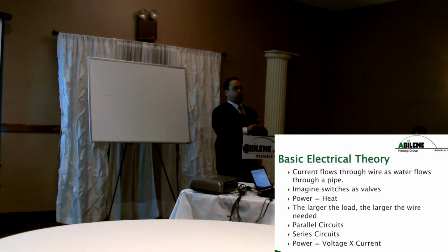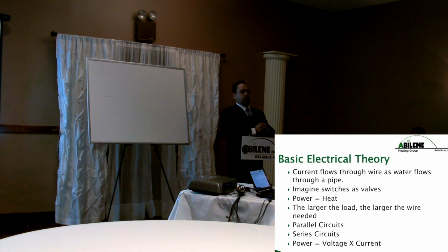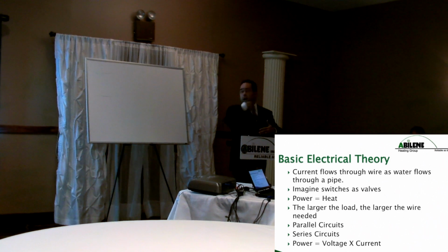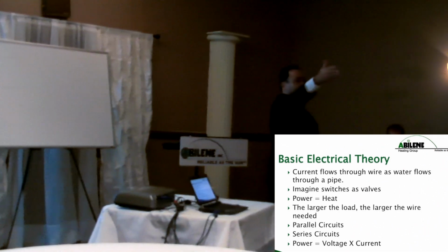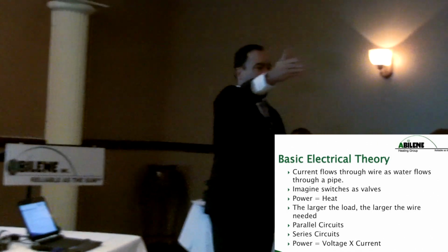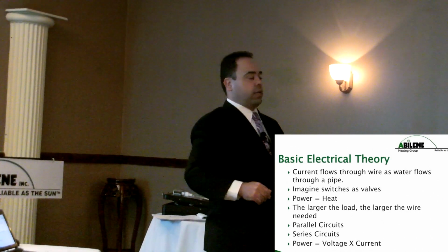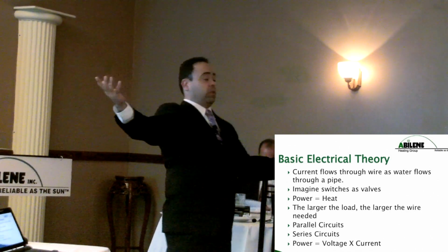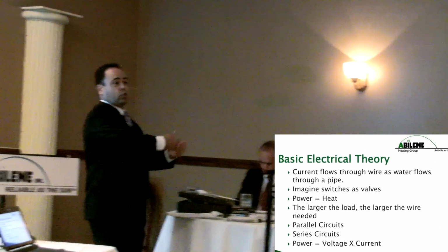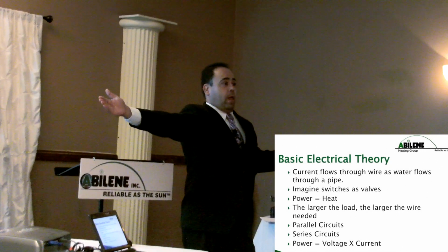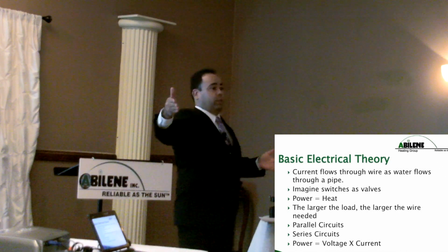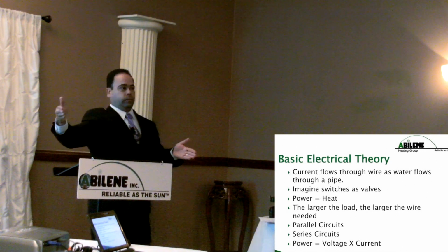More water down the end of the line, the bigger the pipe size. The more power, the larger the load on the other end of the line. If I have a 5,000 watt heater, as opposed to a 1,000 watt heater, 5,000 is bigger than 1,000. So I need a larger size wire to get that 5,000 watts down to the end of the line and run that circuit safely.